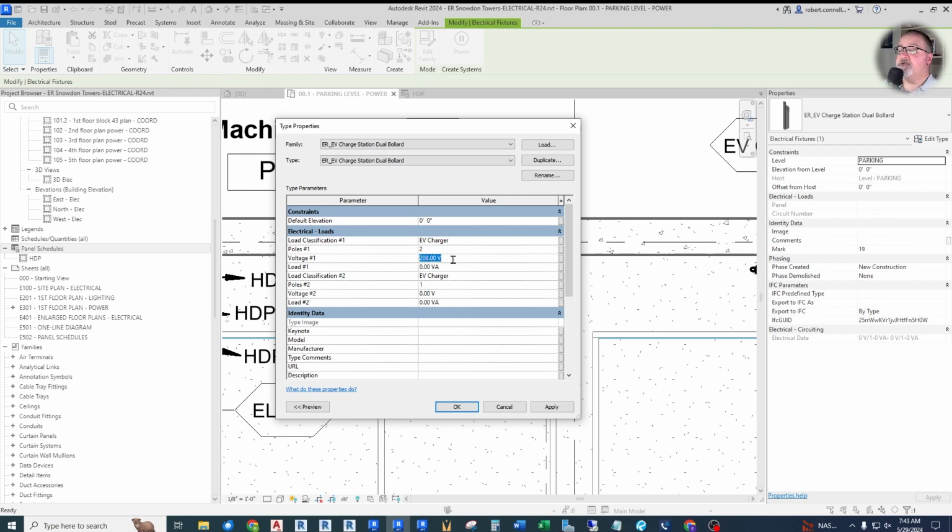These are just level 2 charge points. And the load on these, we're going to do the 32 amp ones. So it's 32 times 360, the magic number for 208 again. 2, voltage 208. And the load, and I just realized I'm wrong. It's not 208 3-phase, we're 208 single phase. So the magic number is just 208 volts times amps. So that helps a lot. 32 times 208. There we go. Close to a 7 kVA charger.